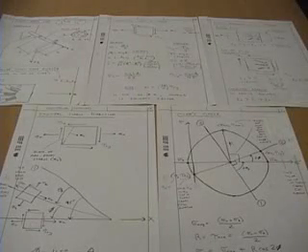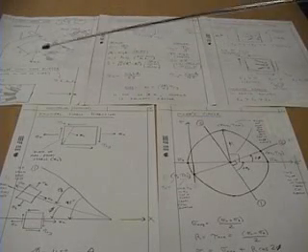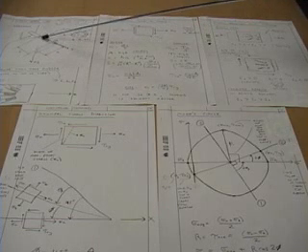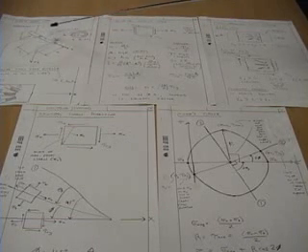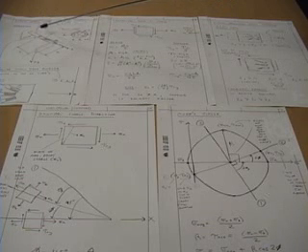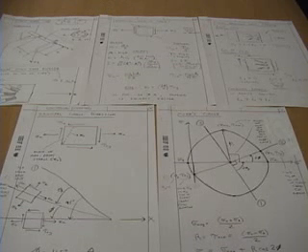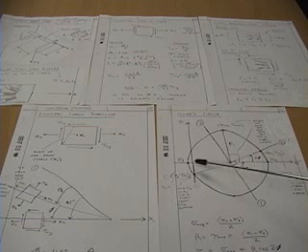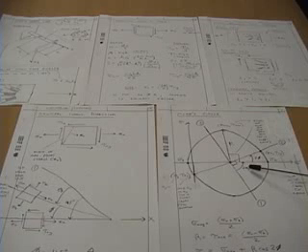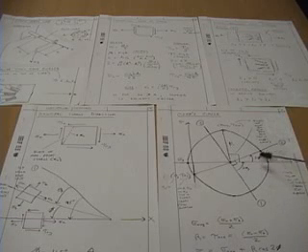Now I'm going to summarize the procedure that's carried out in lab to utilize readings from the strain gauge rosette. We first apply a mass to the end of the tube. That creates a state of stress on the top of the tube, which we're measuring with the strain gauge rosette. So we measure the 3 voltages coming from the strain gauge rosette, 1 voltage for each gauge. We calculate the strains corresponding to those voltages from the strain gauge bridge equation, using the gains properly. Then we calculate the maximum and minimum principal stresses from the strain gauge rosette equations and the angle theta P from gauge 1 to the maximum principal stress.